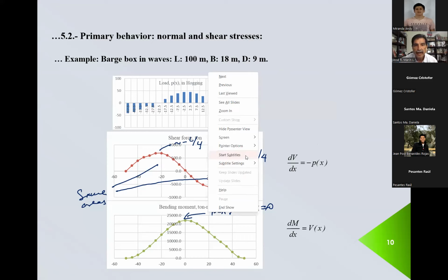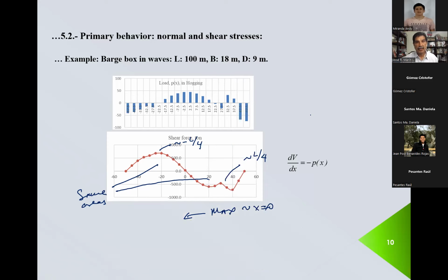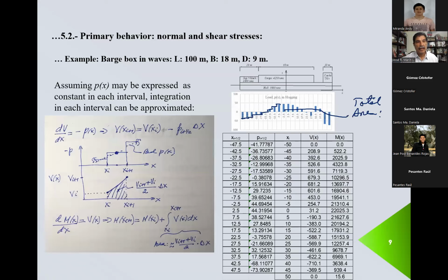What you could do is try, for example, a more efficient integration scheme. You can integrate separately the weight curve and the buoyancy curve, because the weight curve follows this step-like distribution, and the buoyancy changes continuously.